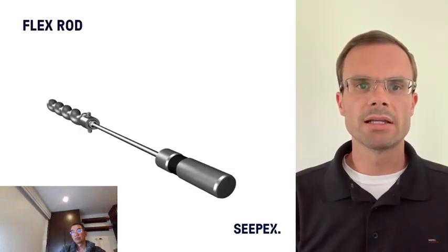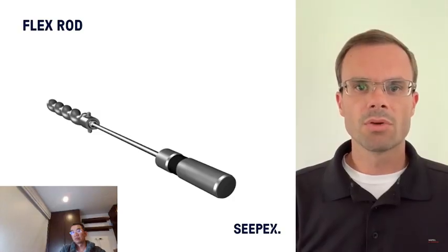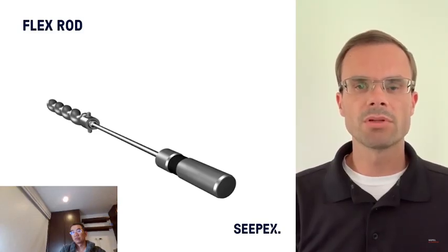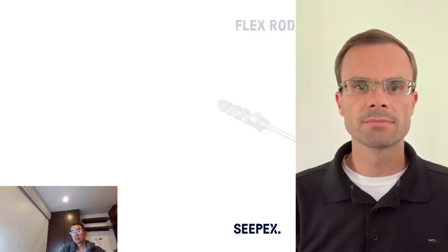This design actually eliminates the universal joints altogether and relies on the flexibility of the shaft to convert concentric motion to eccentric motion. The advantage is that all moving parts are eliminated, but there are limits for speed and pressure. Also, the pump typically is longer to minimize the angularity of the flexible connecting rod.